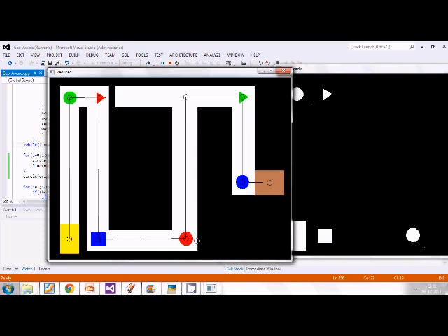This way you'll get around quite a few cases, based on the previous position and the next position of the waypoint. Based on this, you'll get a number of cases, and you can just code separately for each case. Consider each waypoint, consider the previous and the next ones, and based on that you can determine what turn you need to make at that waypoint.